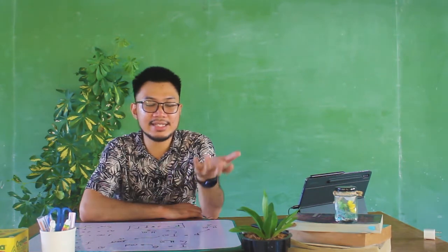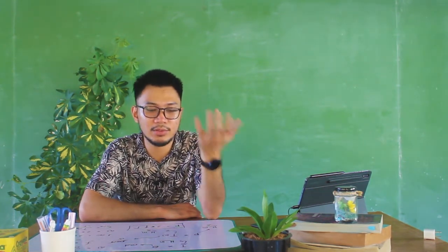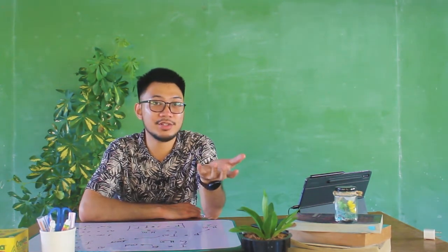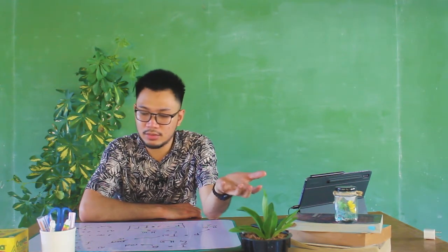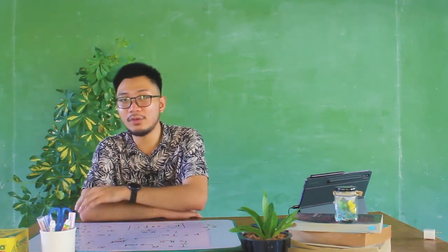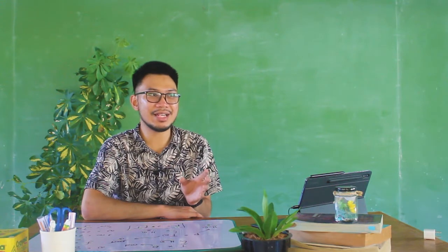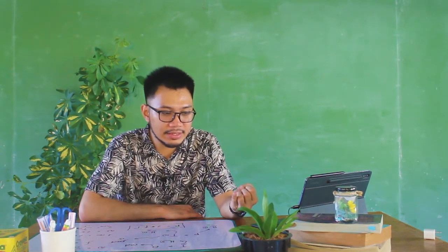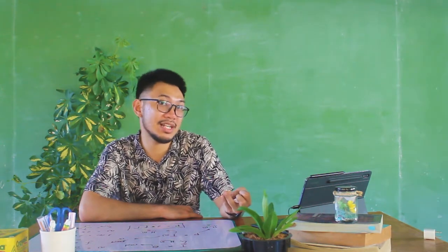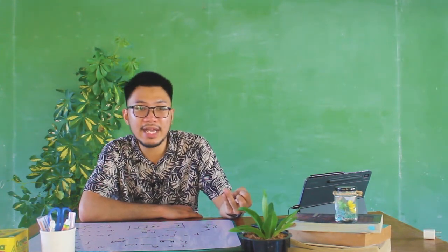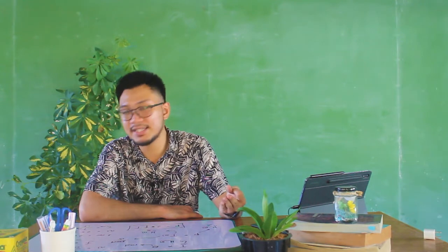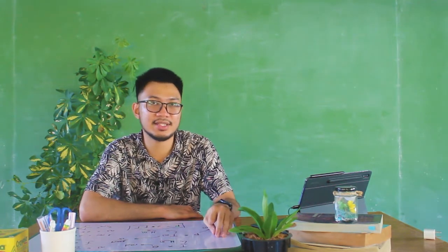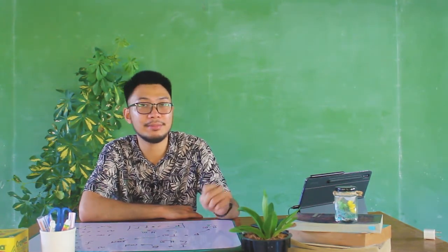So mao na, as engineers, we should be able to design sa mga dimensions sa atong shaft. So, for you to be able to know the radius of your shaft, you should first know the power requirement of your machine and the number of revolutions ng imong machine per unit of time, and also the maximum allowable shear stress of your member.